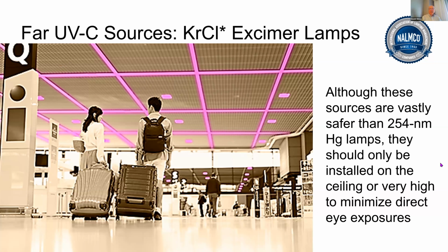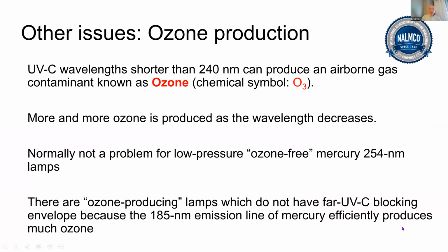And although the krypton chloride lamps are vastly safer than 254, they should only be installed on the ceiling or very high to minimize direct exposure. You don't want to have them on the wall aimed straight at occupants. Then you might run into some complaints, because at high levels, high dose rates, you can actually sense a little bit of dry eye. You have to blink more often. So you don't want to be in that condition.